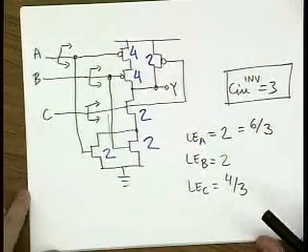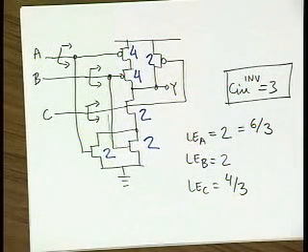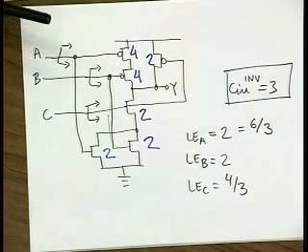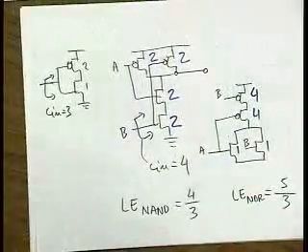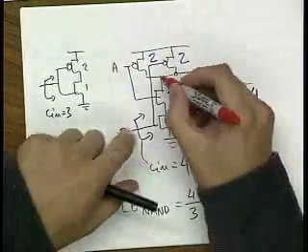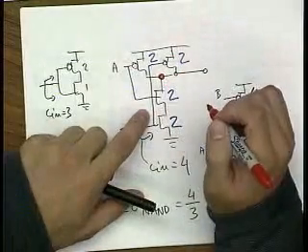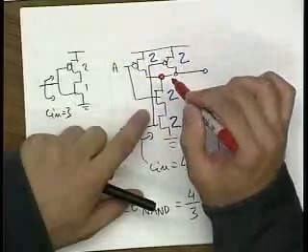And then for the parasitic delay, what you need to basically figure out is just to find the ratio of the capacitances that are connected to the output. So over here in red, I'm going to do the parasitic delay. So basically, the parasitic capacitance that's sitting over here is basically the sum of all the widths of your transistors.